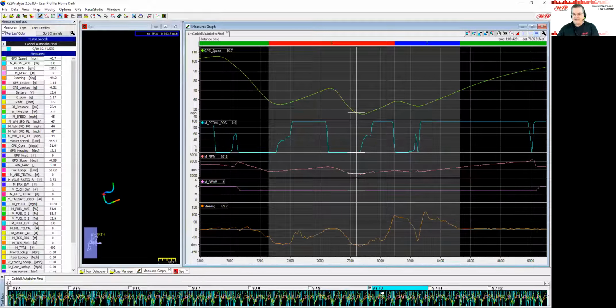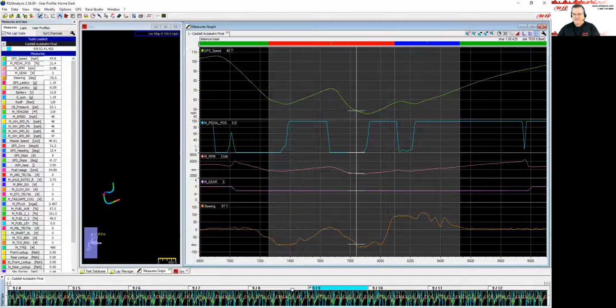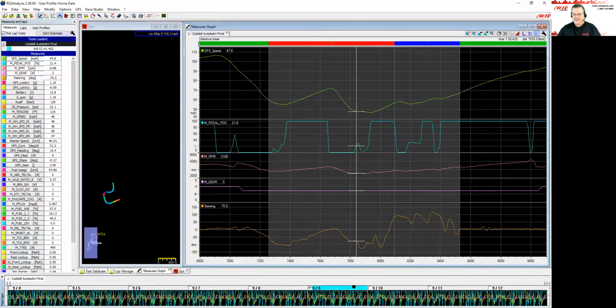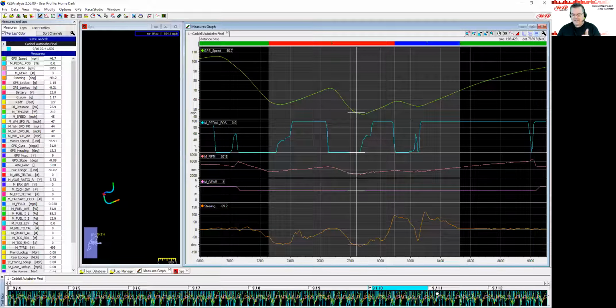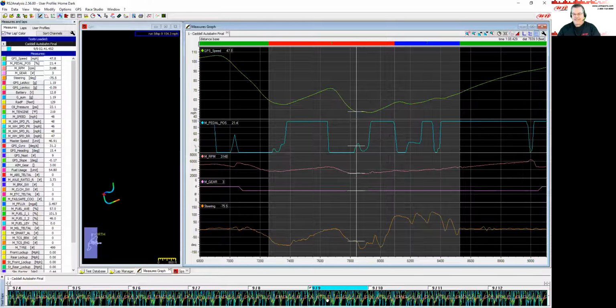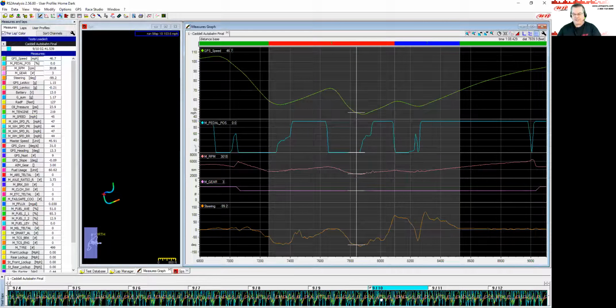And I just drag back and forth on different laps to see if there was a particular lap that he did really well, or laps that he didn't, and then that's teaching me and allowing me to see a lot of data real quickly, and then be able to say, okay, that one there, why did he have to get out of the throttle? Let's dig into it. Was he faster or slower in the middle of the corner? Did he just get over anxious, a little too greedy? Whatever it happens to be. This little trick about keeping your eye up in the main window and dragging this Lapse toolbar laps back and forth is a very quick way of looking at how you approached a certain corner. So a little tip there.